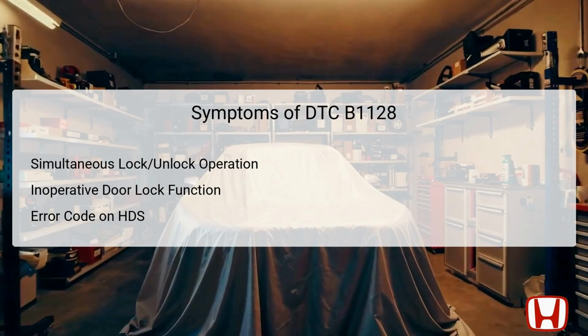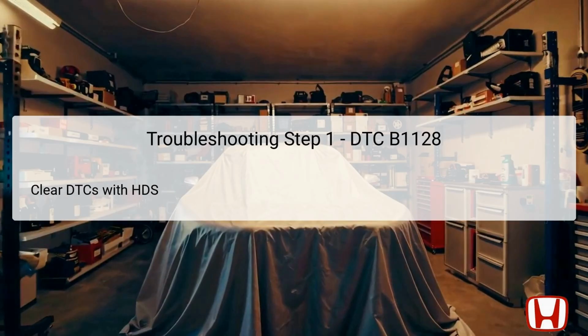The first step in troubleshooting DTC B1128 is to clear the DTCs using the Honda Diagnostic System (HDS). This process involves connecting the HDS to the vehicle's diagnostic port and following the necessary prompts to clear the existing trouble codes. Clearing these codes resets the vehicle's diagnostic systems, allowing you to monitor for the return of the B1128 code.